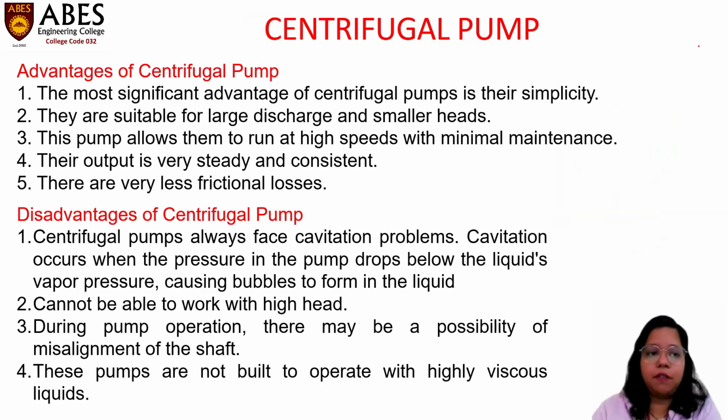Some advantages of centrifugal pumps are, the most significant advantage is the simplicity of this pump. They are very suitable for large discharge and smaller heads. The pump allows them to run at high speeds with minimal maintenance. Their output is very steady and consistent. There are very less frictional losses.